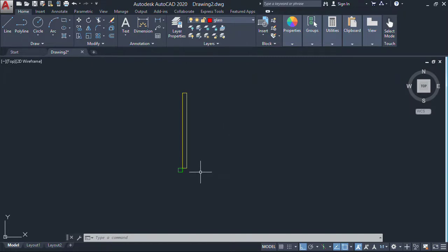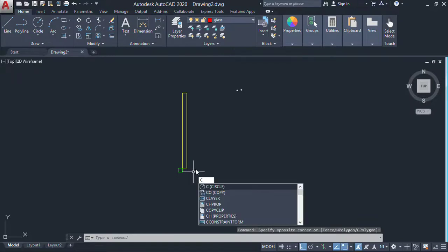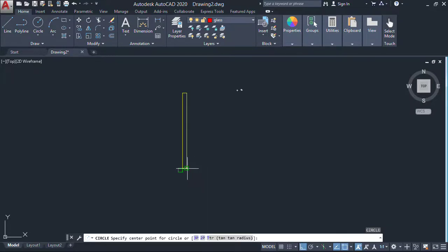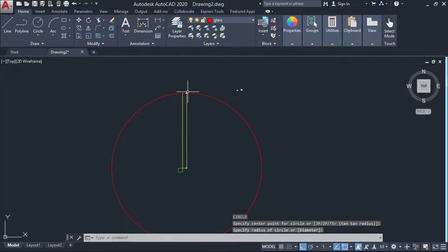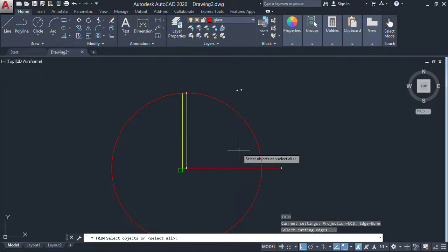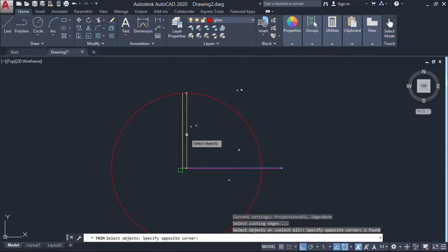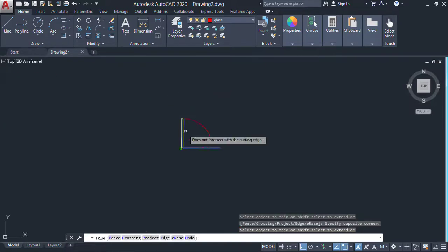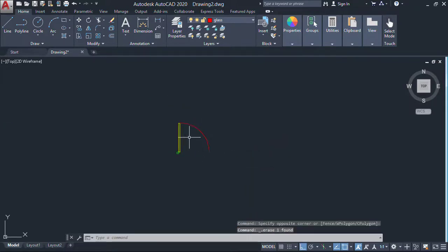So this is our door, but since we show the opening and closing of the door, I'm gonna choose another line. It's better to be another layer, but since I want to use just another color, I'm choosing glass for you. So all you're gonna do is click on circle and choose your first point, second point, and then delete or trim whatever is extra. Since I want to keep what is inside this one, I chose these two lines and I'm gonna delete the rest. So this is gonna be my door.